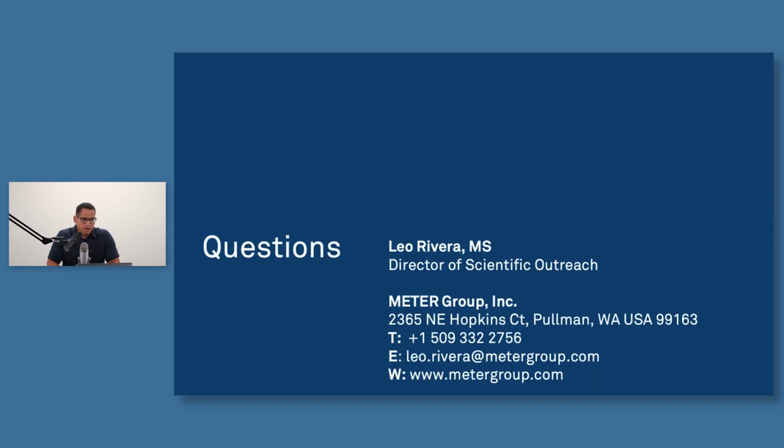But then thinking about installation within the root zone, of course, that is absolutely critical, and you need to understand the rooting depth of your plants. For example, in our turf application, we know that that turf species doesn't root deeper than 15 centimeters. If we were dealing with some more drought tolerant native species, we would need to go deeper than that because they're going to root down deeper.